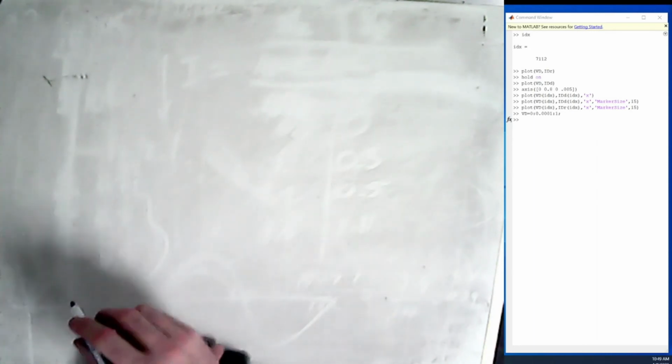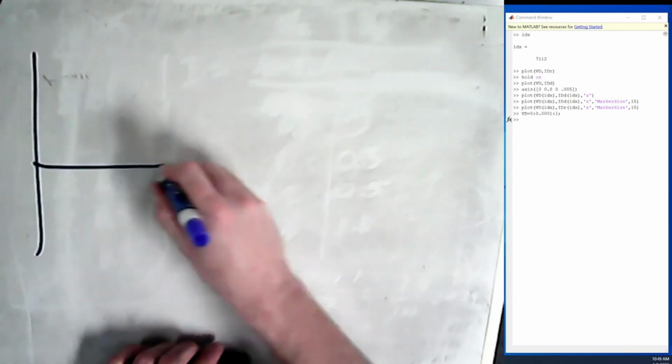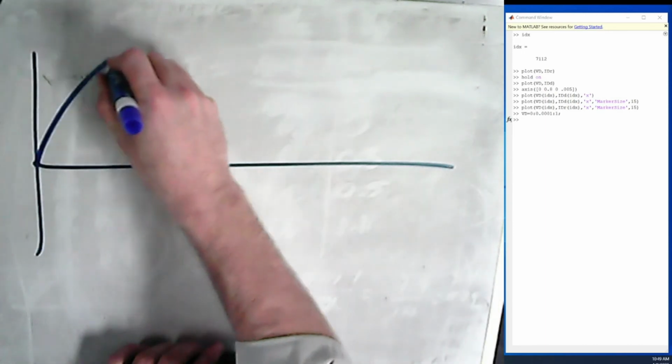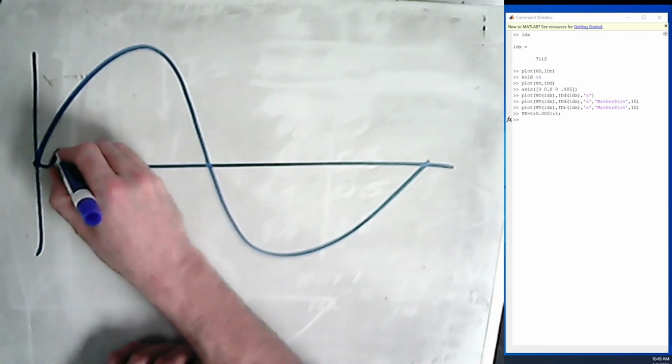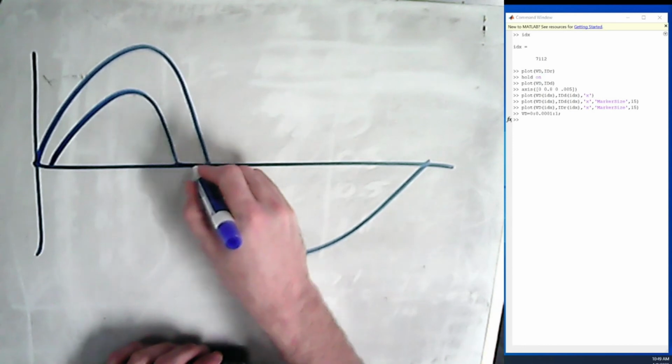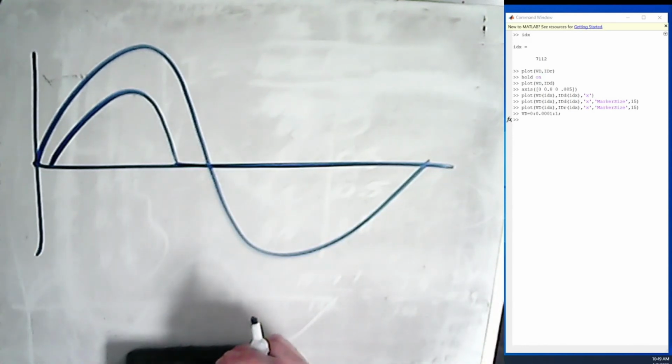Half-wave rectifier, we get half-wave rectifier, okay? We're going to draw this kind of big. We're just going to do one waveform, like this. Half-wave rectifier, you're going to end up with something like this that has a 0.7 volt drop. Obviously, if you get into like 20 volts, 0.7 volts is less than 10% of that. You know, it's less than 5% of that. And so that's going to cause a little heartburn.